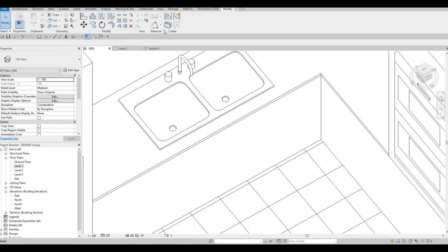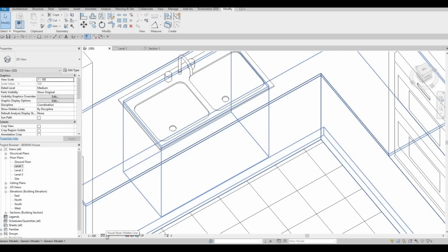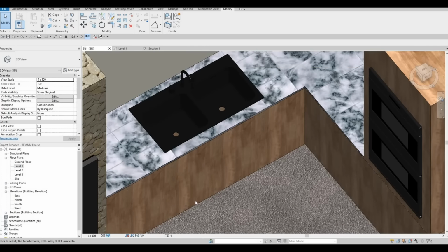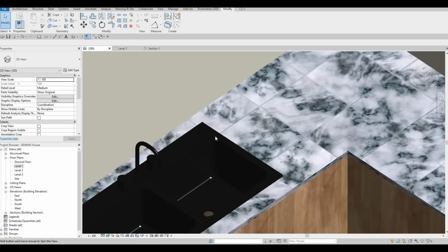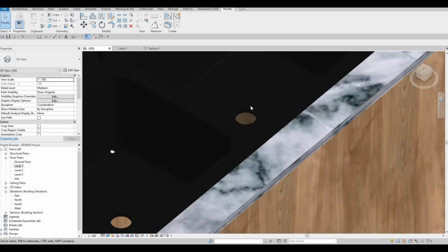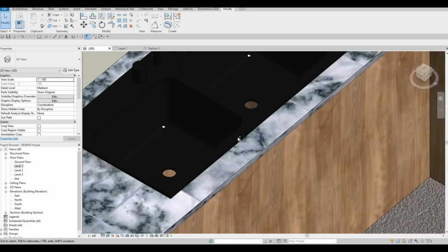So once you click on cut geometry, you will need to select the void extrusion first, and then the top here. So now if we go back, you will be able to see that we have done the cut geometry properly, and it's still showing like that.